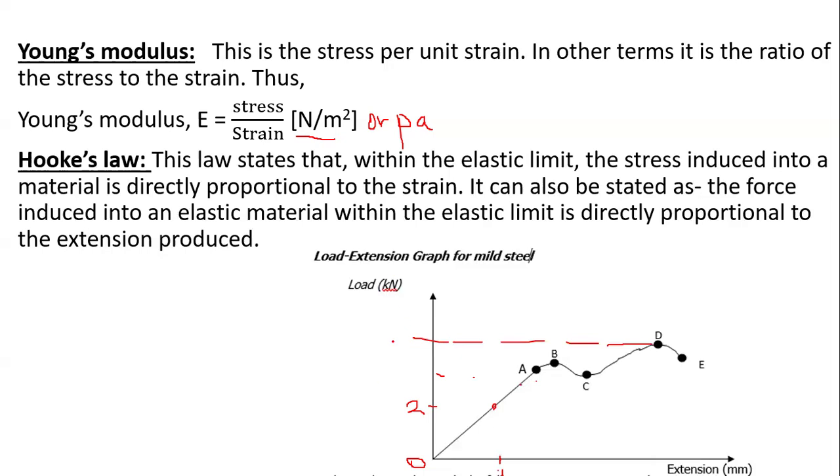representing the force that we can use to calculate the highest stress, the maximum stress, or the ultimate tensile stress for a material loaded in tension. That is the stress at point D. When you continue loading, you will see similar behavior to what we saw here, meaning that your material is now about to snap or break in two. So point E is our break point, meaning the material finally gives in.